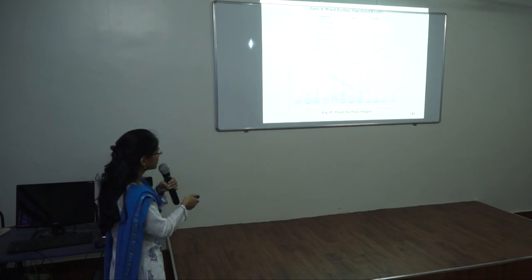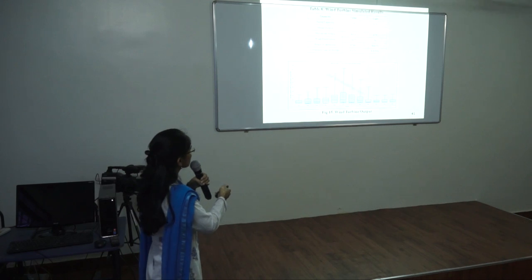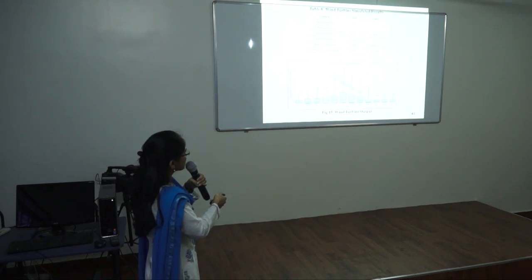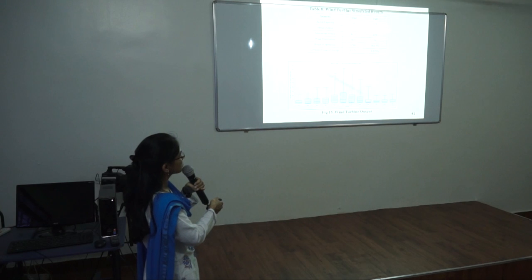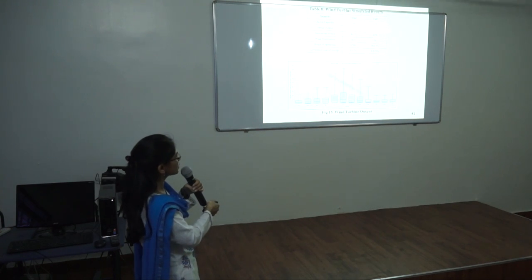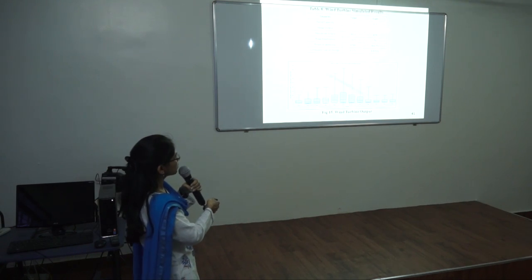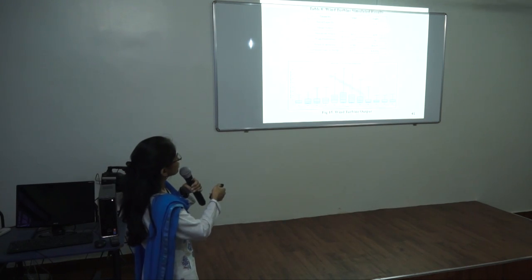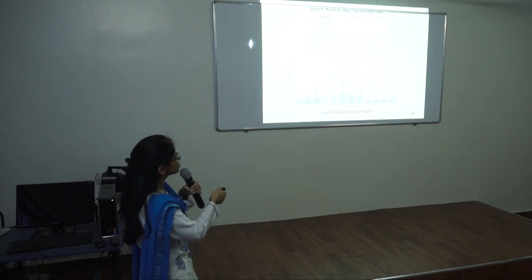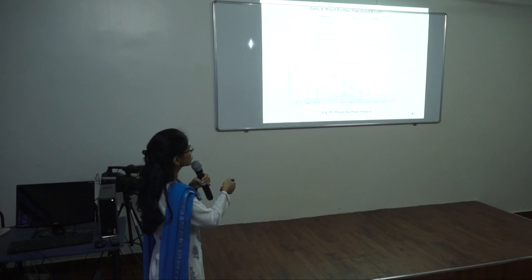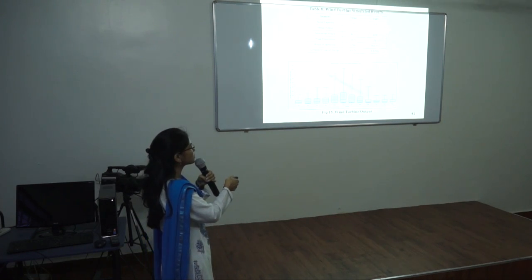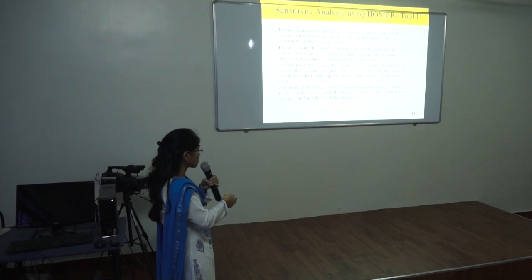This is the output of the wind turbine. Here we observe that the highest power output by wind turbines is relatively higher during the months of May, June and July due to an adequate amount of wind velocity being available, while for the remaining months the output of the wind turbine is very low. The mean output is about 4.99 kilowatt, maximum output is 84.2 kilowatt and the levelized cost of energy is about $0.171 per kilowatt hour.